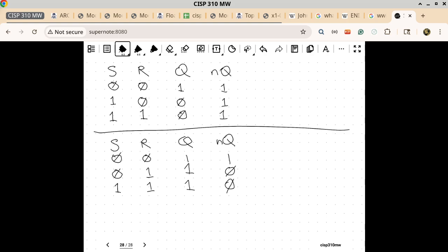We observed that when we combine AND and exclusive OR gates into the half adder and so on, the input would completely determine the output. If I give you the input, you already know what the output would look like. But in this case, that is not the case, because when the inputs are both ones, it is simply retaining the state from before.